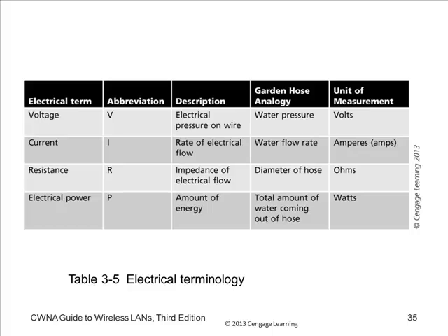Because if you have an under voltage, a brownout, what's the power supply going to try to do? Maintain the same power. If your voltage goes down, what happens to the current to maintain that same power? It goes up squared.